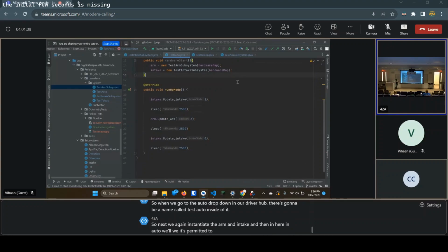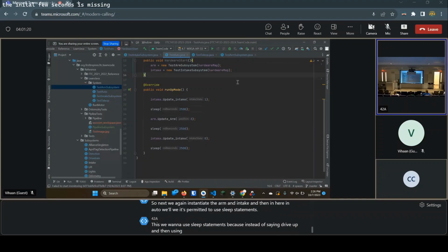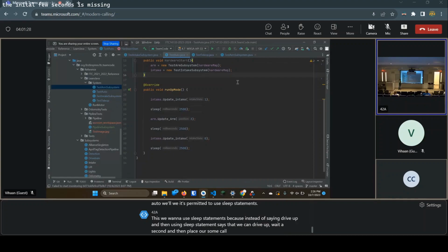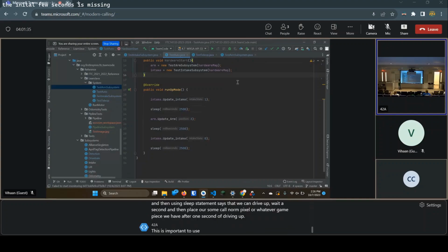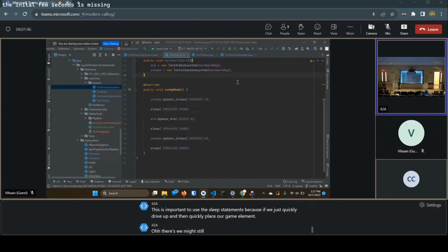In this example, we open the intake using intake.update, wait 2.5 seconds, that's in milliseconds there, then move the arm to position 3, which we don't need to worry about, wait 2.5 seconds, and then close the intake. So this could be autonomous if you want it to be, but rather than that, you would be moving around.